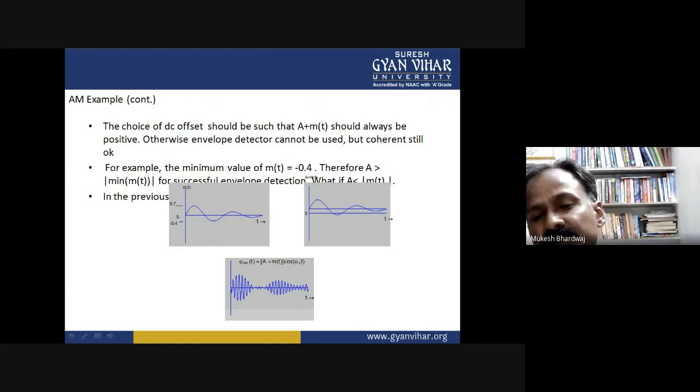We had already discussed multiplexing. I had already told you it is the simultaneous transmission of many signals through a single channel. So multiplexing is a technique in which several message signals are combined into a composite signal for transmission over a common channel. In order to transmit a number of these signals over the same channel, signals must be kept apart so they do not interfere with each other, and hence they can be separated easily at the receiver end. Multiplexing is basically of two types, frequency division and time division. And the third, which we had already discussed, is code division, CDMA, for multiplexing.